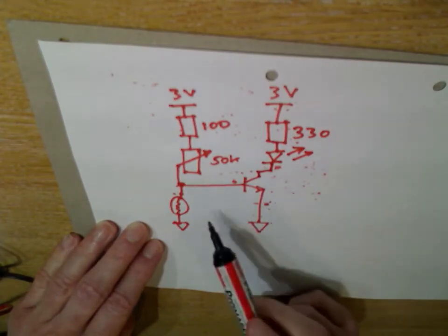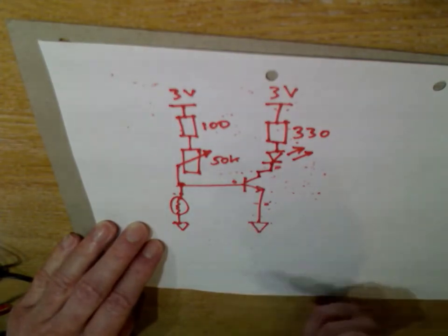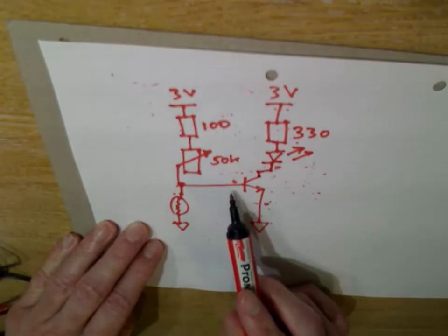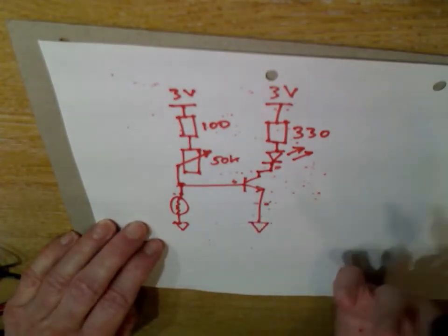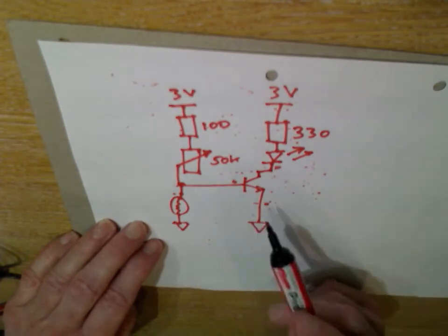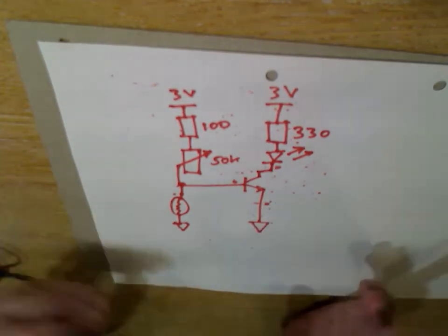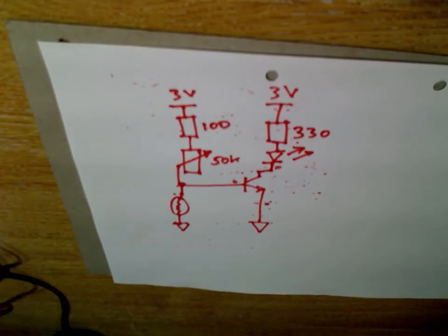Now of course we've made some simplifications in that we're assuming that the thing turns on at 0.7 volts. It won't go strictly on or strictly off. There'll be a transition period, but it's a simplifying assumption we've made, and we've got to make some simplifications.